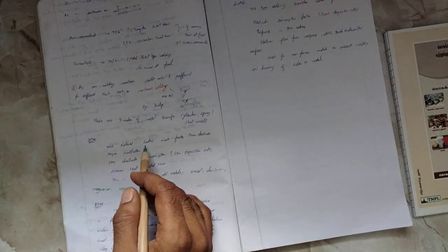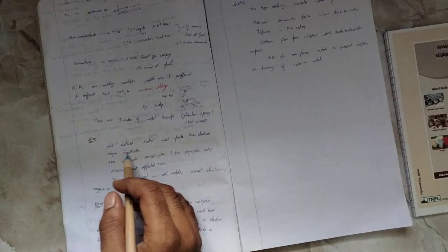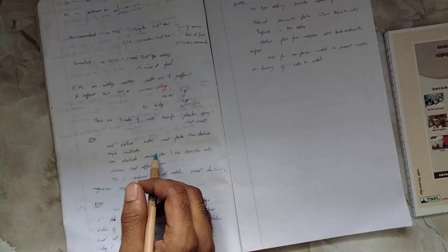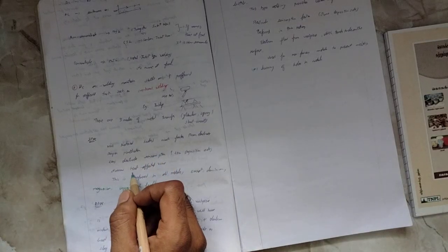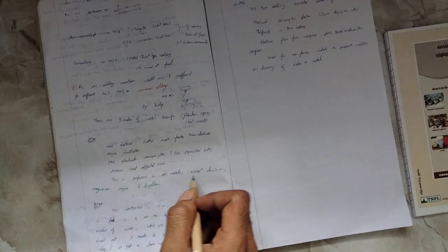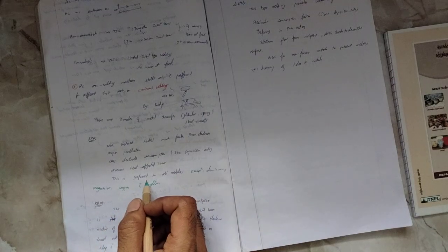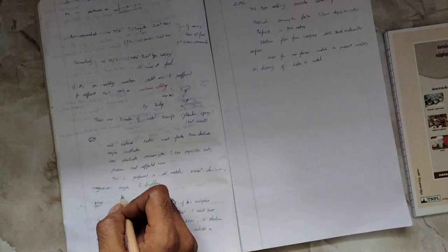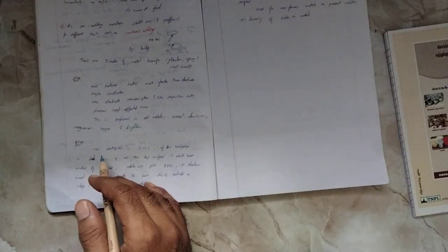So you can see the work material heats and moves faster than the electrode. Yes, definitely, it means straight polarity and deeper penetration, and less electrode consumption. It gives a narrow shear heat-affected zone, and this is preferred for all metals except aluminum, magnesium, copper and beryllium. So straight polarity is generally used for most of the materials except aluminum, beryllium, copper and magnesium.